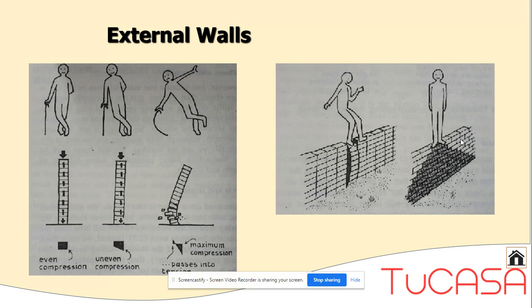So the vertical loaded wall is all in compression, and these little stress diagrams here illustrate the distribution from those vertical loads. And we've also got, of course, horizontal wind loads, thrusting and side thrusting from roof and floor members as well.